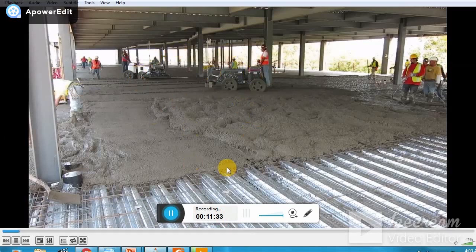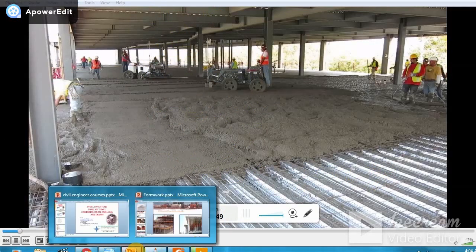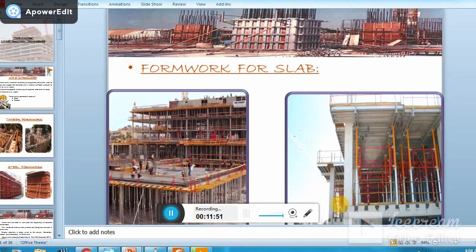This machinery load, this concrete load, all these corrugated sheet loads are now taken by what? By these steel girders, because no shoring is provided. In this concreting process there is also no shoring provided. So that's why we call it unshored construction.